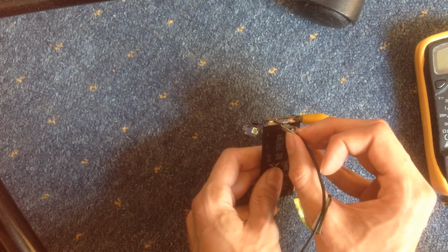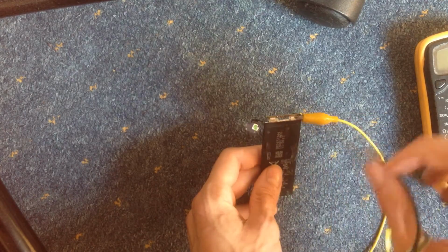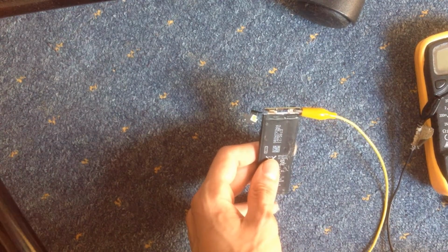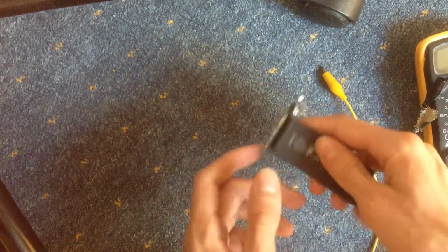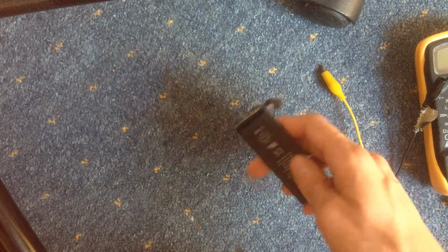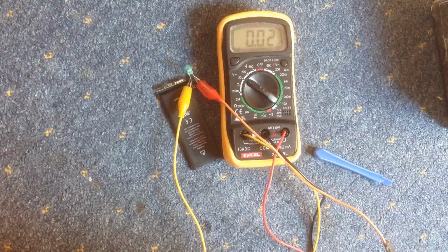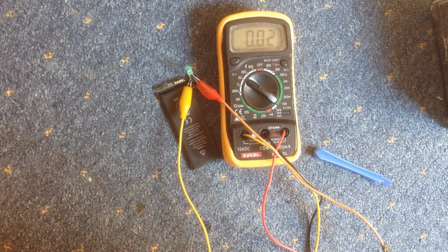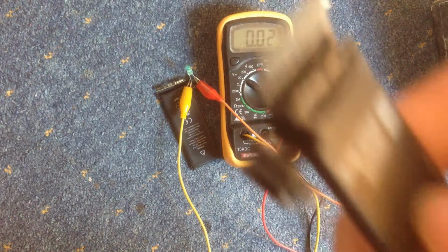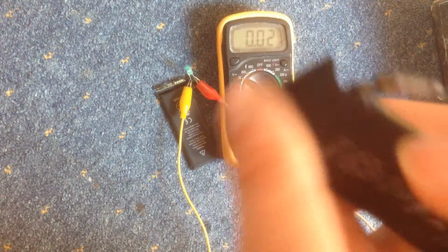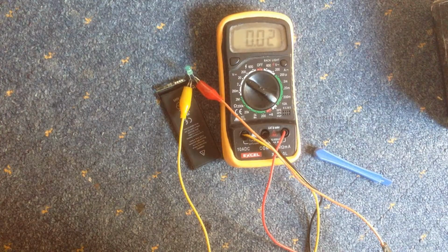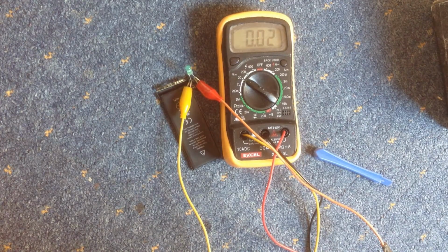As you can see, it does spark a bit, but that's okay. And after you're done with that, just check if there comes any voltage out, and that's what I'm going to do. As you can now see, no voltage is coming out of it, not even the slightest. So you just have to measure those contacts here behind the actual circuit. If no voltage is coming out, your iPhone won't work with it. That's because it doesn't even detect the battery.